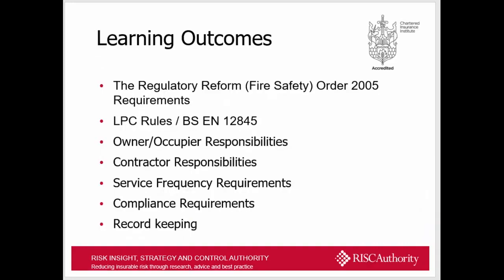Also included within this webinar, to meet the requirements of the CPD award, I have to provide you with the learning outcomes associated with this webinar. So the learning outcome that we're trying to understand and establish today is the requirements under the fire safety order. I'm going to go into a quick brief on the LPC rules and BS EN 12845, the requirements for owner and occupier, the responsibilities for the contractor, the service frequency requirements and what's got to be serviced and maintained, so that you have an understanding of the equipment that you have and when it should and should not be maintained.